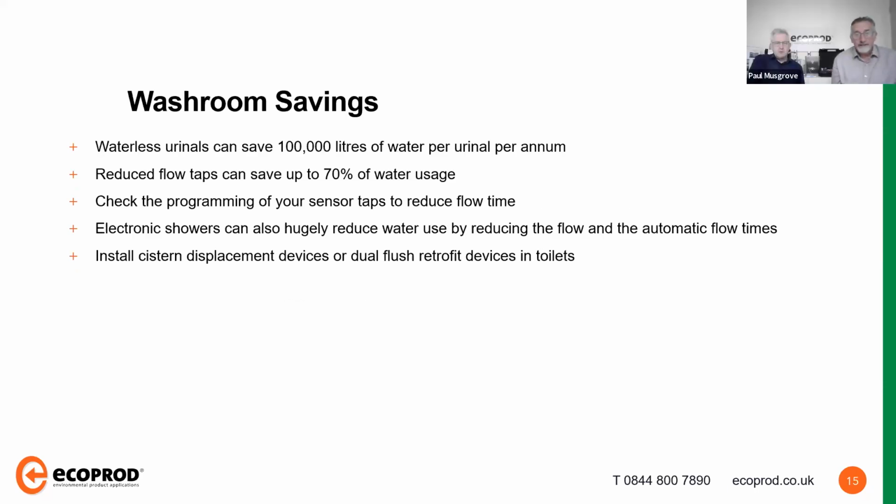So, washroom savings: waterless urinals save 100,000 litres per urinal. I put a post on LinkedIn this morning questioning why you would use fresh water to clean an existing urinal. Why not change, save yourself money, get a return on investment? Taps, 70% on average. Programming sensor taps is really interesting. The technology has moved on vastly.